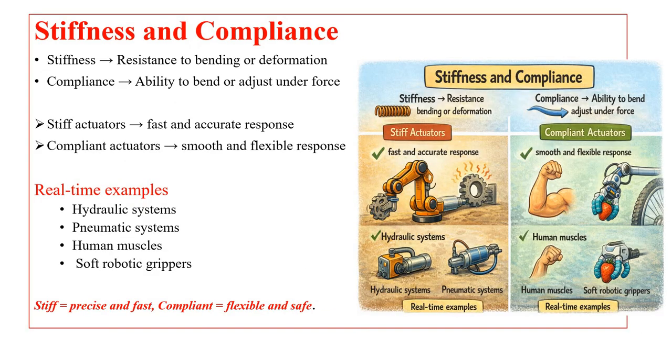And the last characteristic is stiffness and compliance, where stiffness refers to the resistance to bending or deformation, and compliance is the ability to bend or adjust under force. Why do stiffness and compliance matter? Because stiff actuators have very fast and accurate response, whereas compliant actuators have a very smooth and flexible response.